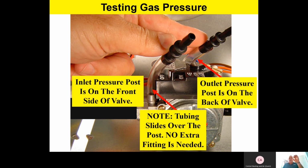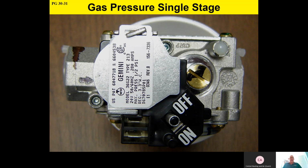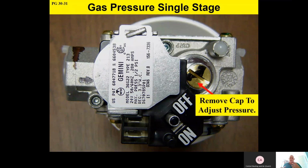You'll note that the tubing slides right over that post, and you don't have to have an extra fitting to read gas pressure. So as you take a look at the gas pressure for single stage, if you had your little handouts there, pages 30 through 31 would describe those gas pressure settings. But to actually take that gas pressure setting, what you're going to do, you're going to remove the cap from the gas valve to adjust the pressure. This is on a single stage valve.